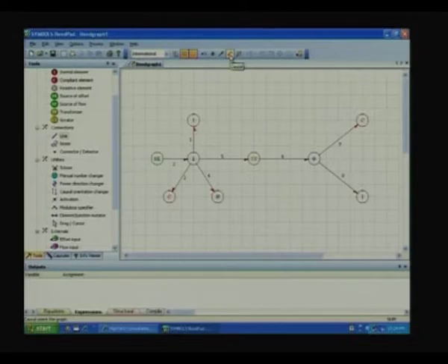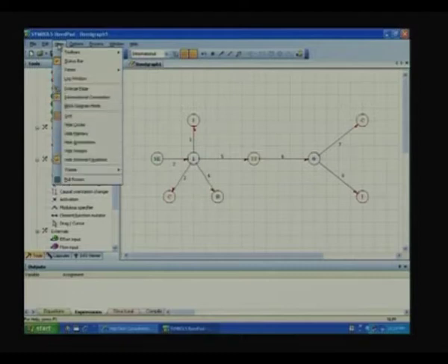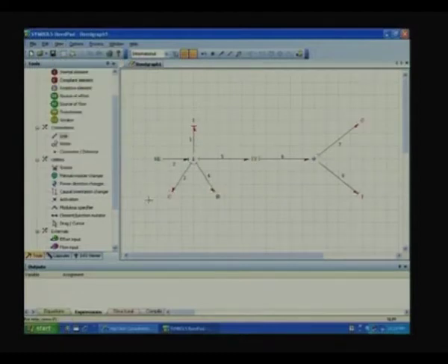Now, this is the icon for causality that can also be done in an algorithmic way. So, I press it, it has already given the causalities, probably because these are all circled. So, I will hide the circle, view is hide circles. So, you can see that this is properly causal, the stroke is here, SE is receiving the flow, C is receiving the flow, R is receiving the flow, flow is going this side, flow is going that side, exactly as you have done on the paper, it is causal that way.